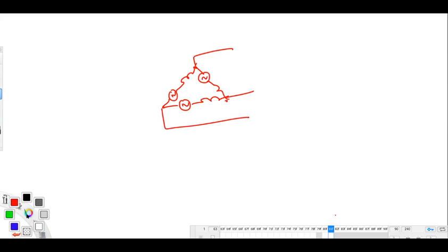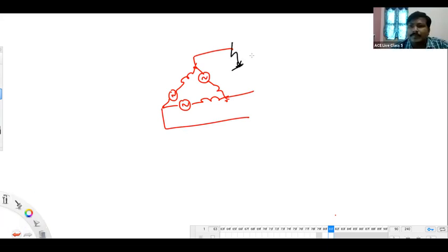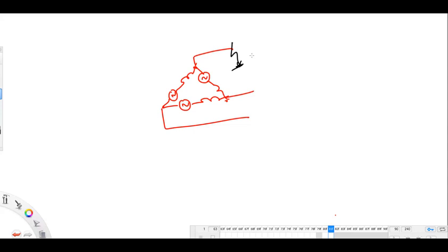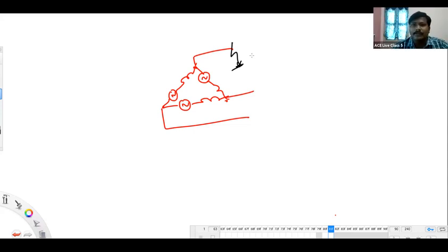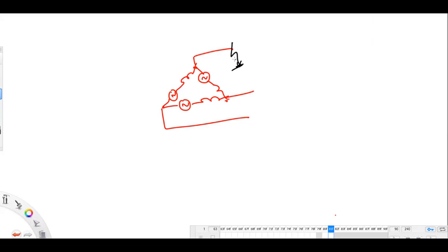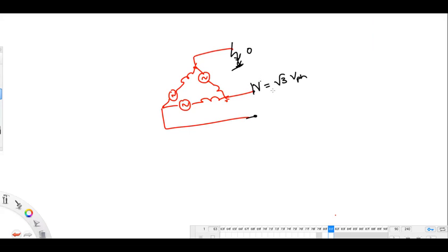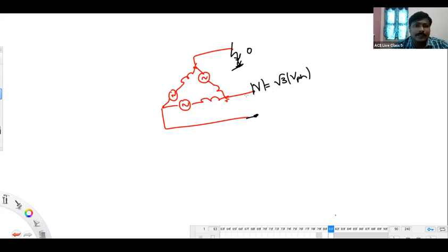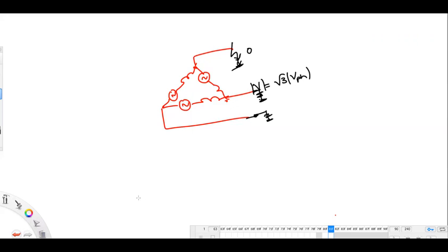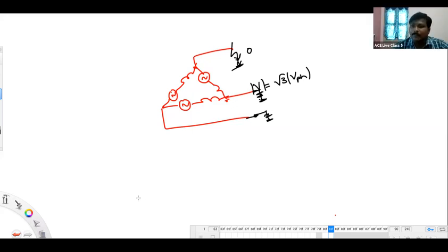But unfortunately, if you have a single line to ground fault at the terminals of the alternator, in a delta connection there is no current at all. And not only that, remaining phase voltages will be rising to their line-to-line values. That will be like an isolated neutral condition, which we discussed. Then that will lead to insulation flashover of the insulators connected between this phase and ground in the tower. So that's a problem. To overcome this, we have to provide a better neutral path, so we go for only star grounded alternators practically.